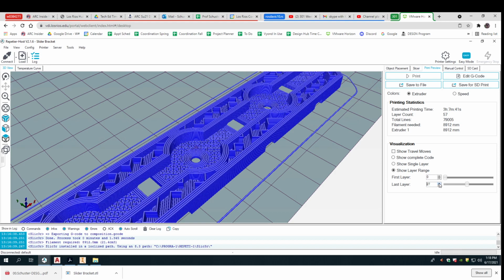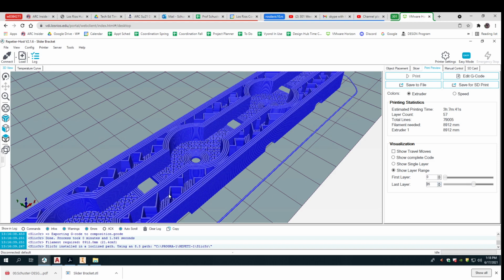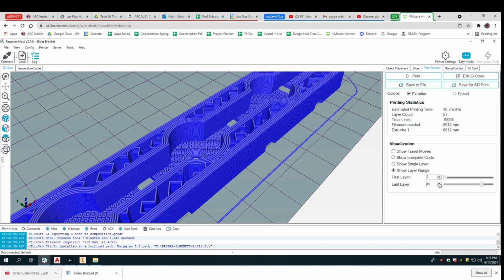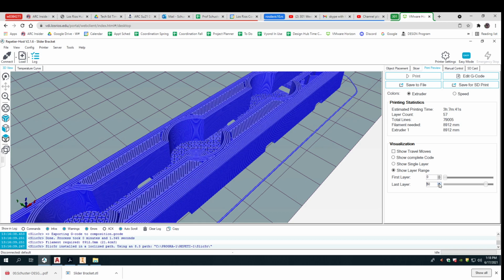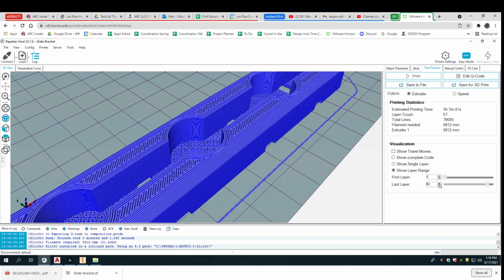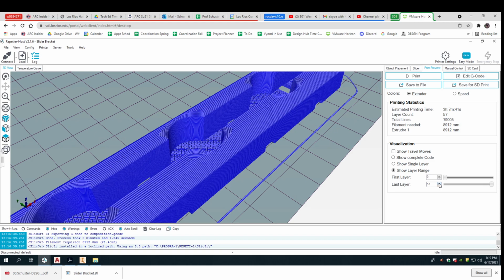And you can see it just goes up layer by layer by layer. And this is what I'm talking about, the infill. And see, 1, 2, 3, 4 outer perimeters. And it did 4 layers. And the top layer was that. And then it just keeps going up and up and up. And now it's suddenly closed itself off. So 3 layers of just doing that. And there we go. And that'll be my part when I'm done.